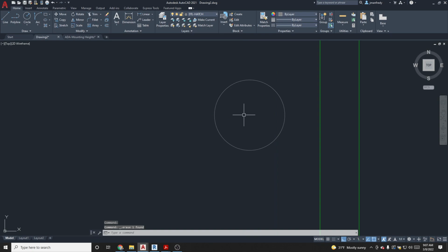And we're drawing a handle. So I'll draw a line from the center of the circle. If I hover on the circle, it finds the center right there, a little dot. So I click, and it finds that dot. I move my mouse to the left. Again, I'm on ortho. Here's ortho at the bottom. To the left, let's say 6. That looks pretty long. Let's move this dot back to the left 2 inches and make it 4. Let's make it another inch. This is 3 inches, not 6.